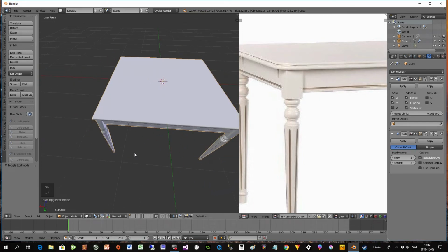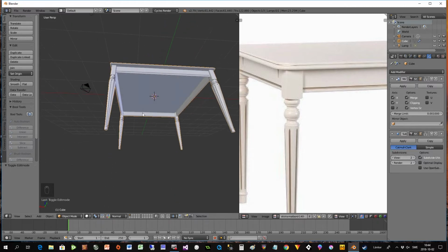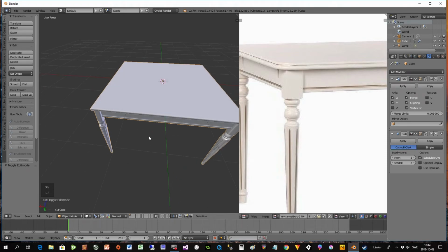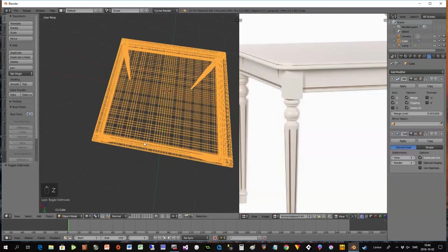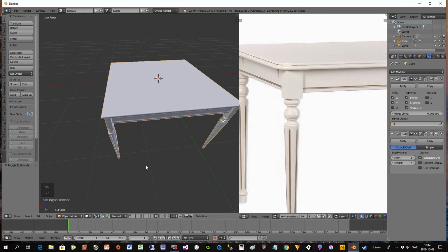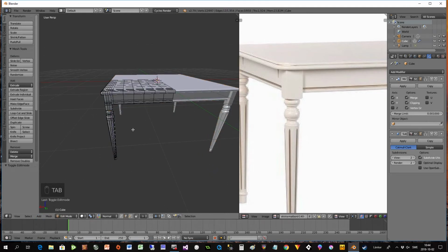And I can show you one more thing, and that is to make a really nice cloth up here. If I now press set, this is how it looks, and that is because I have used Subdivide twice. And I will do a little bit of a trick now, and I will also save some polygons. So I go back to edit mode, pressing Tab.